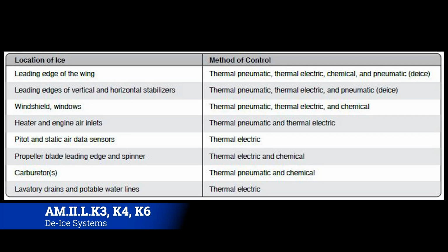Okay, so there are 4 basic ways that you can prevent ice, or fight ice whenever it starts to form. There's heating surfaces with hot air, heating by electrical elements, and then breaking up the ice formation, usually by flexible or inflatable boots, and then a chemical application.